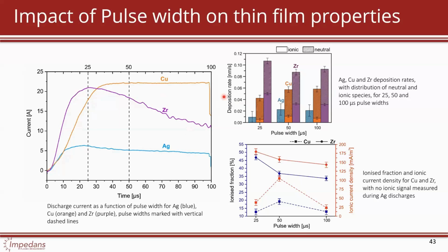Like yeah, there are some people who try to strike a plasma with a metal instead of even using argon, or only having argon on for a short amount of time, like pulsing the argon. There are people who pulse temporally. There's actually people who pulse spatially. So there are some Czech groups that do spatial pulsing, and then you can also pulse the gas. So you could have the argon just on for a moment and then turn it off to help minimize this effect.